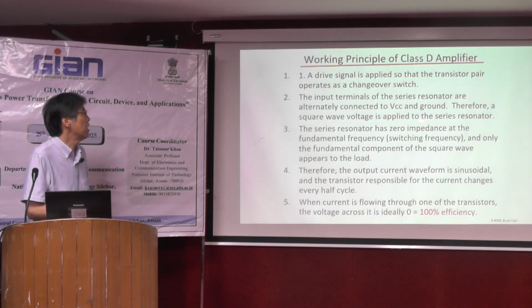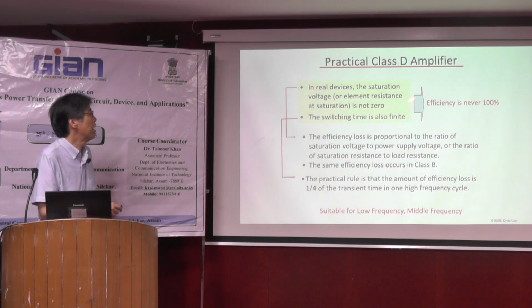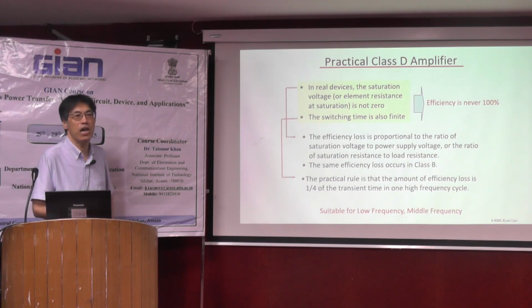This is the working principle of the class D. Theoretically, we can reach 100% efficiency, but unfortunately in the real device, we have a saturation voltage, and the switching time is also finite.